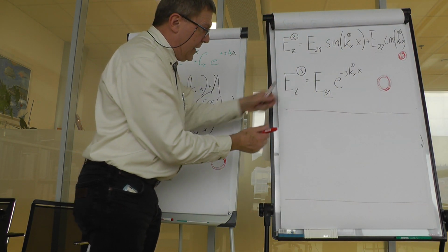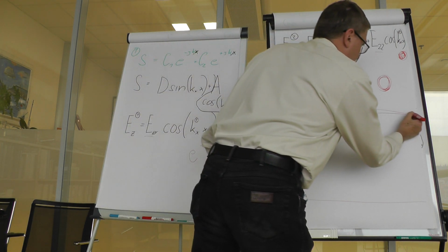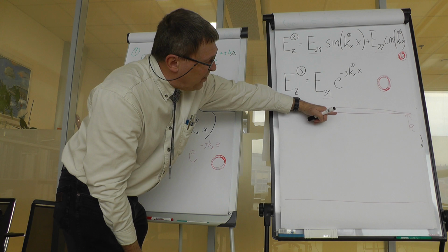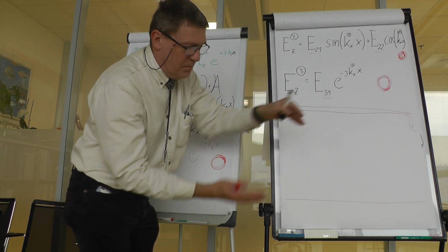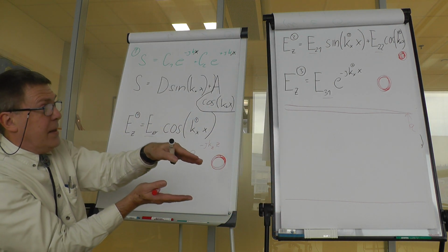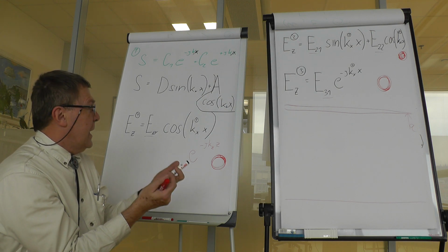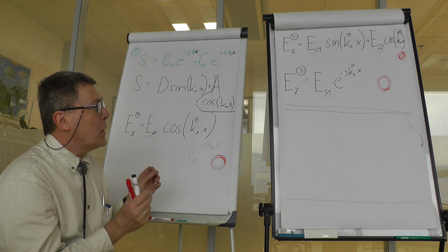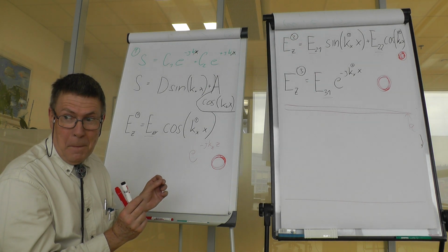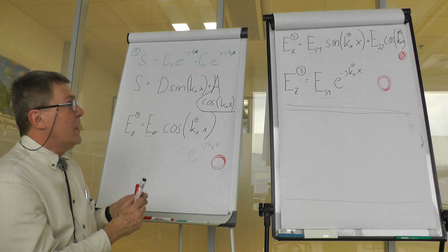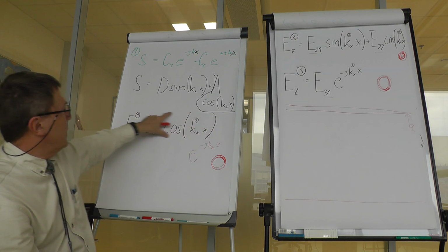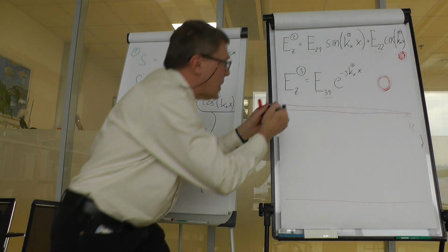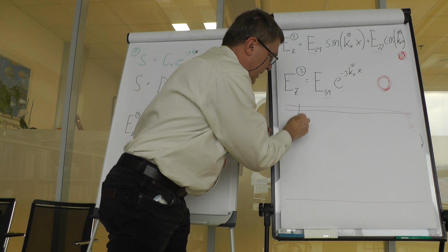So let's say at the boundary where we have the x-coordinate equivalent to A, just at the boundary between the filling of the waveguide and the enclosure, metallic or other layer on it, at the inner boundary, the x-coordinate is equivalent to A according to the picture I have made at the beginning. So we can express field components at this boundary. Namely, we will know that from the inner side, another remark, at this place we will choose only one position so that we will make a cut at some z.